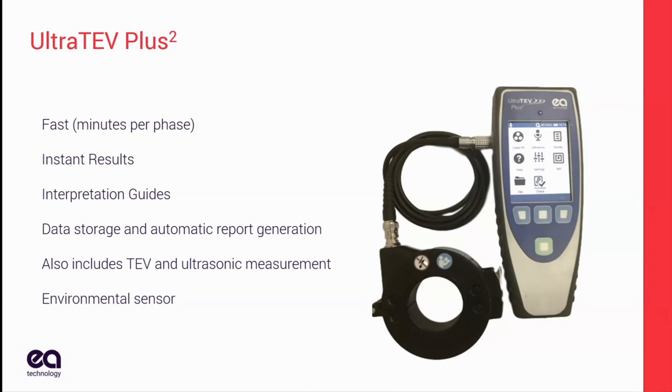It's going to give you phase resolved plots, waveforms, and a variety of algorithms that are going to try and point you toward PD or not. You can record the data and then Wi-Fi it to somebody who's an expert, or you can take a survey, and when you're all done, sit down at the computer and do all your analysis there. So it's a bit more flexible. It does more things. It does one phase at a time, so it takes a bit longer, and you're doing the analysis yourself. So those are the two different product options. They work in tandem depending on what your application is.